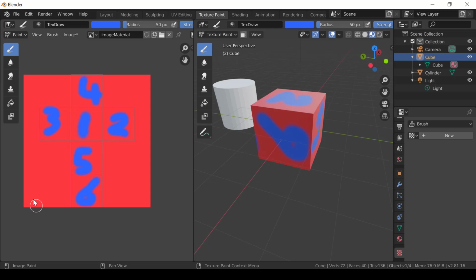Here, this is the UV, this is the U axis and the V axis, and each point in the UV has a representation in the mesh axis as vertices. So each vertex has a location in the UV, and the UV is connected to its location in the vertices. So let's say this is number 6, and these vertices, let's call them 1, 2, 3, 4, for example. Then you will find they're connected here as 1, 2, 3, 4 points in the UV system. So it will take the image of the number 6 and stick it on the cube.